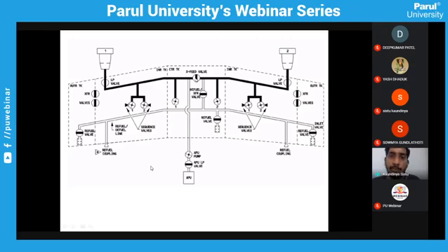The cross bleed valve is nothing but a valve between both the engines. If you open it, it will go like this and into the APU. If you open this APU valve, it will go into the APU. But from here to here it is traveling a long way, so the pressure will drop. So you need an APU pump to start the APU engine.